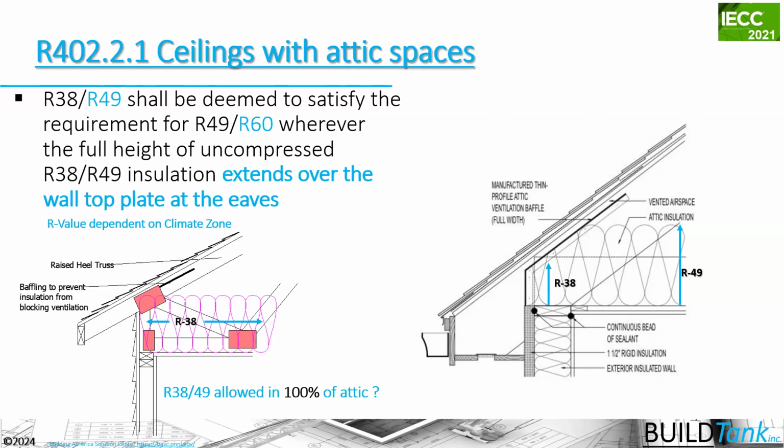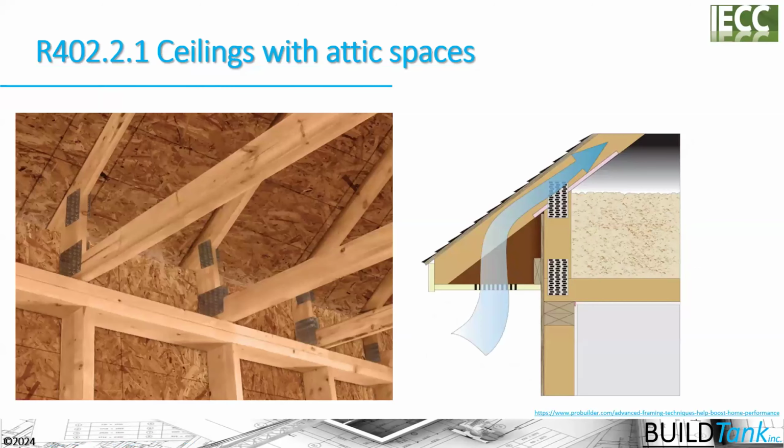One is that it fully covers the top plate, and the other requirement is that we have enough heel height in order to receive the insulation at whatever required R value there. So we really should be looking at energy heels on all our plan reviews to ensure that we have the proper amount of insulation over the top plate that the builder proposed to put in that particular location.